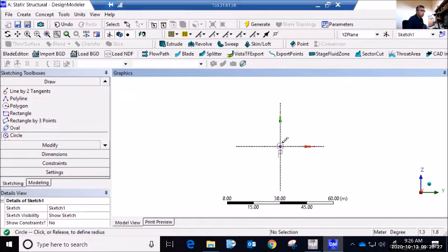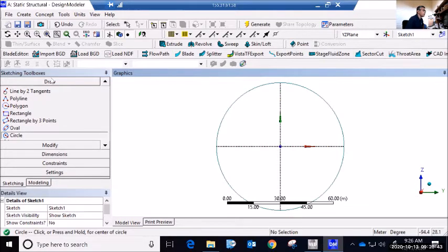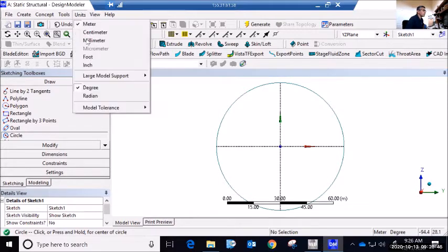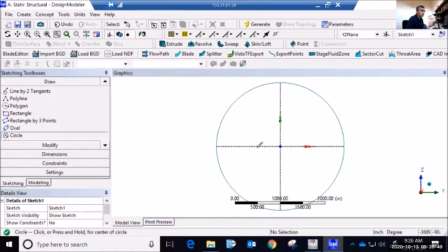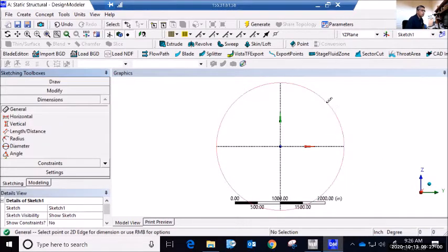I look at the ruler and I'm working in meters. So this is going to be a huge section. So I'm going to make it as small as possible. I think I have to change my scale. So I'm just going to leave this for now. And I'm just going to go to my units and make sure I'm using inches. We want to change in inches. This is 2000 inches. If I go to dimensions for my sketch, D1, you see this is 2000.